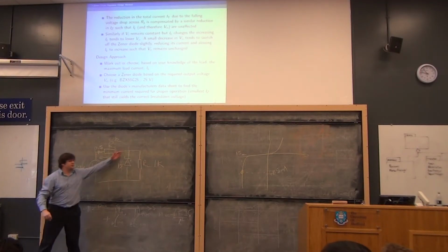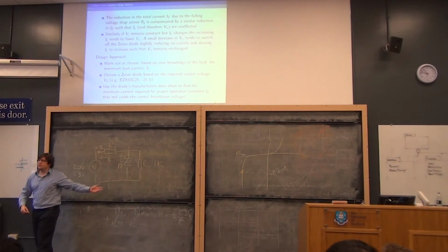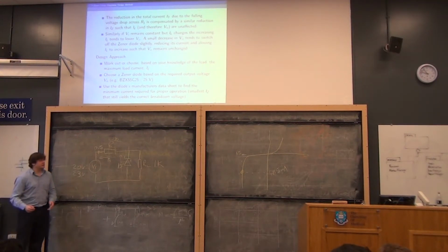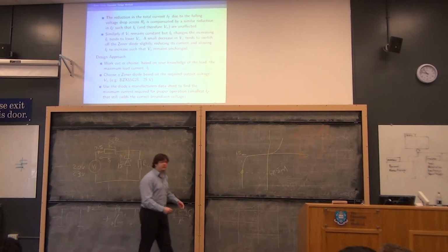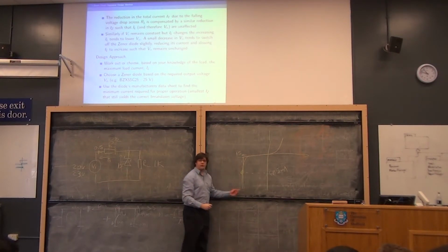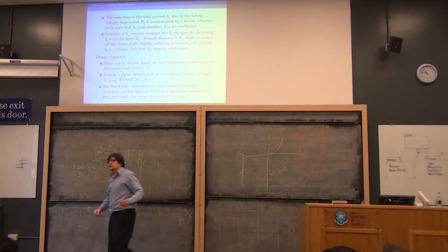And this won't really be 15. But when you're doing the working out, you say it's a 15 volt Zener diode, I will always assume 15 volts. So what you're secretly saying is actually the curve doesn't look like this, it looks like that. Which is very similar to what we said about the conduction state problems in the diode.